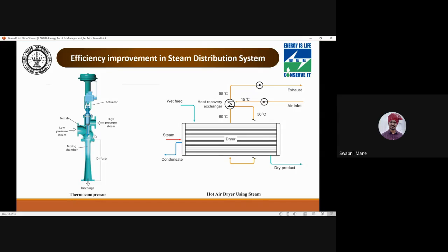Okay, you understand that the pressure cooker is there. Pressure cooker will generate steam, and when it passes through a pipe, there is a condensate there. But if you put the condensate in the open air, what happens is that when it comes in contact with atmospheric air, there is a pressure drop, and the condensate gets converted into flash steam because of high pressure, and then there will be no condensate. It will be flash steam. That means low pressure steam. And this low pressure steam is of no use to us, because it will not have any temperature, or it will not have any pressure.